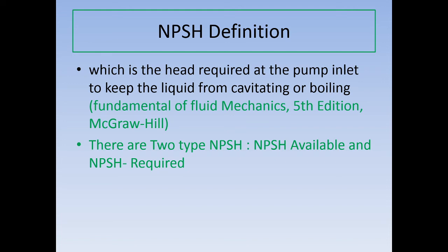The available pressure given to me is already reduced from 9.5, for example, minus 4.5, and now becomes only 5 meters available. And I deduct again the environment vapor pressure at that specific point, 0.4, for example.